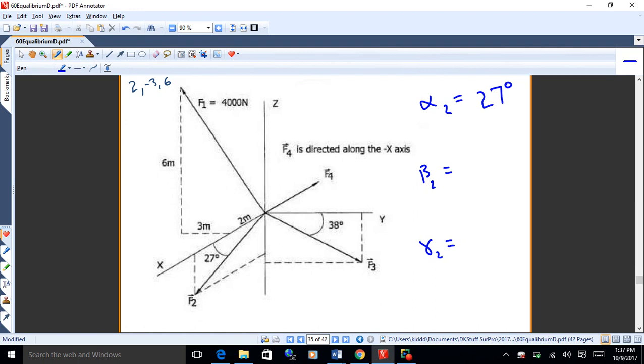All right, now those dashed lines are the key to understanding or visualizing this. What we're doing here is we're coming off the z-axis in the x direction, aren't we? Because this dashed line is parallel to the x-axis. And then the other dashed line is coming down from the x-axis, like so, and that's parallel to the z-axis. So we're coming down from the x and the z direction, and we're coming over from the z and the x direction. So it looks to me like that vector F2 is in the xz plane. Okay, that's the key to this.